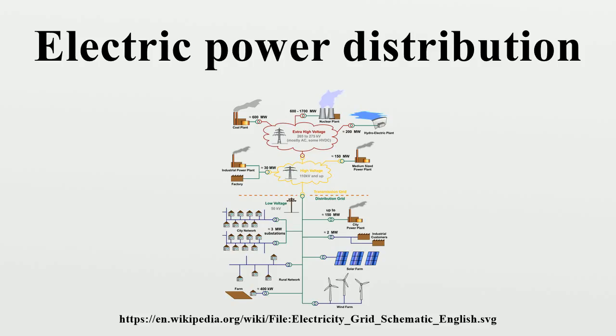However, multiple connections between the utility ground and customer ground can lead to stray voltage problems. Customer piping, swimming pools or other equipment may develop objectionable voltages. These problems may be difficult to resolve since they often originate from places other than the customer's premises.